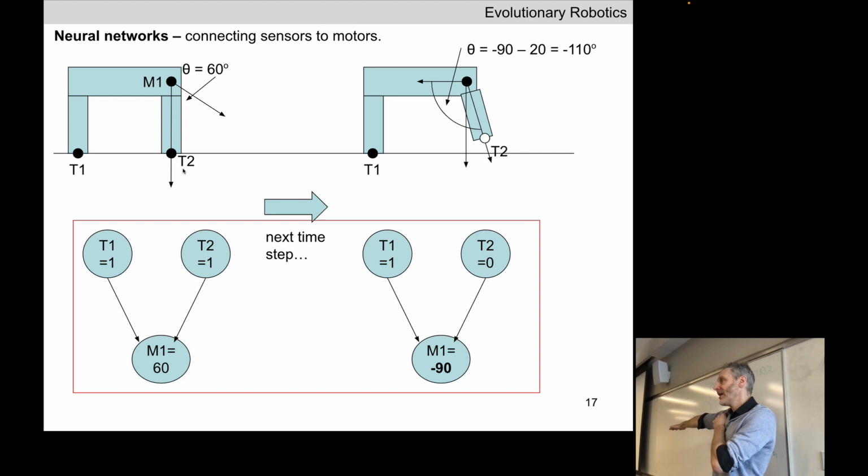Yeah? Okay, so we have a value of 60, and the current angle is 0. We want the position or the angle of that joint to be 60. So the physics engine is going to apply forces to these 2 connected links, the torso and the upper leg. In this example here, at the next time step in the simulation, those forces applied by the physics engine have started to change the position and 3D orientation of the leg, but in this cartoon here, the torso hasn't moved very much.